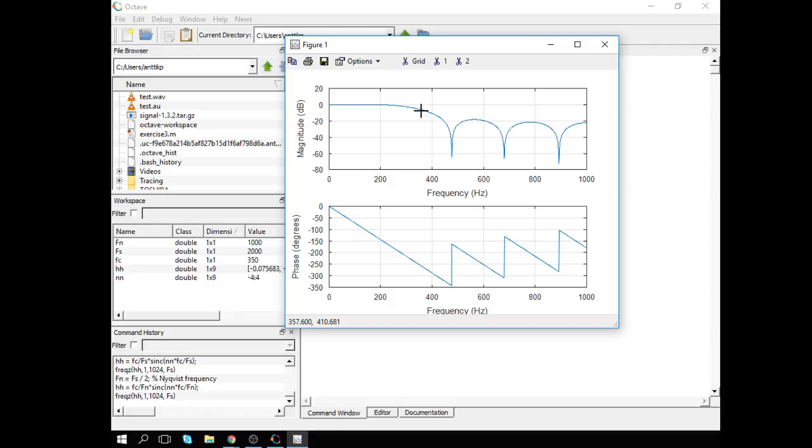The only bad thing is that this ain't much better than any running average filter because the stop band attenuation is not that great, only 20 dB. We can do much better stop band attenuation with the same number of parameters. For example, I can take a triangular shape window. That will be easy to manage.